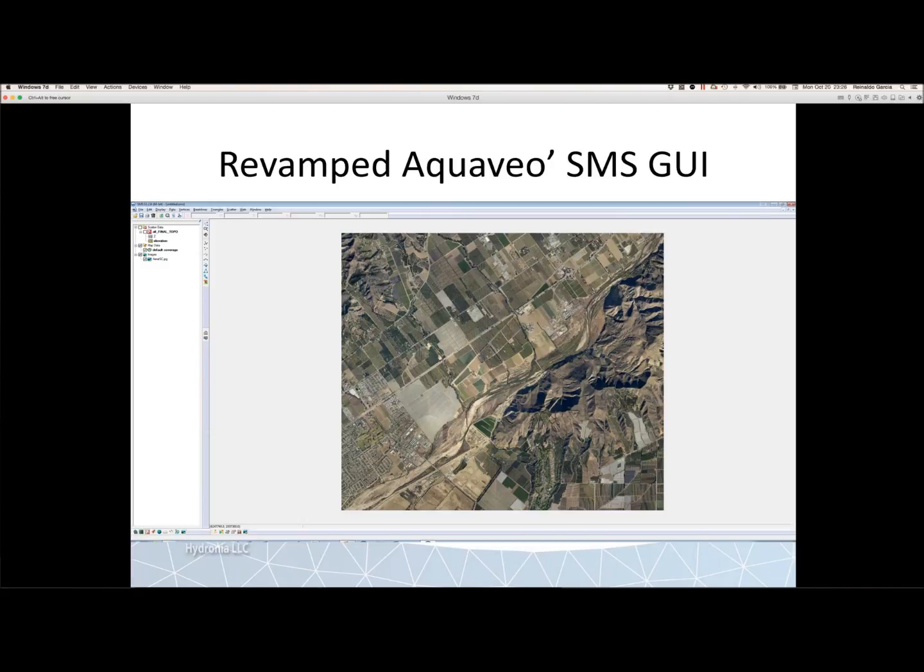You can have a single pipe with maybe 1,000 locations where you want to make analysis of leaks, and they can be performed either simultaneously to see the joint impact they have, or you can go one by one, and you can set up a single setup of the model that will handle all those simulations with no or minimal user intervention.